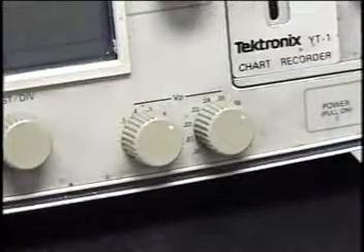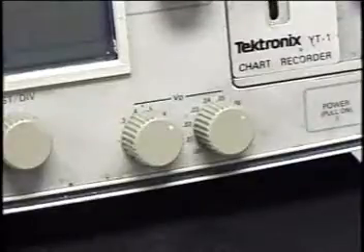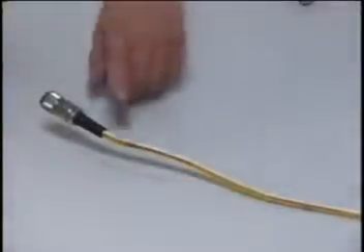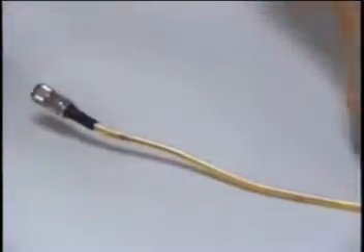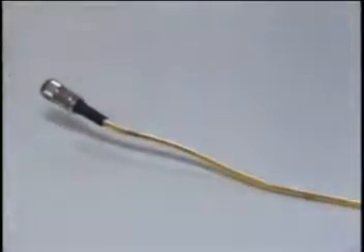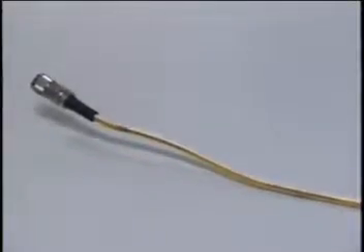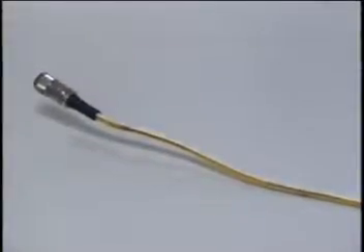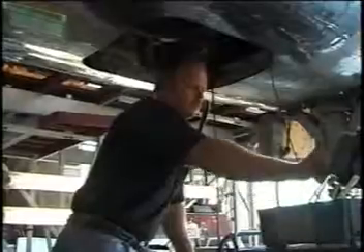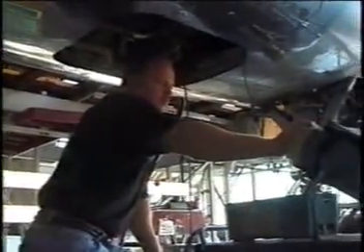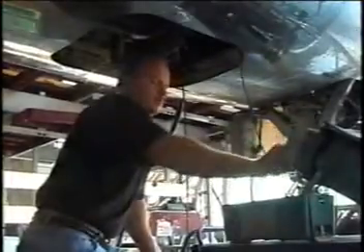With the cables properly bled and connected, you must then select the correct VP, or velocity of propagation setting. VP is the speed at which a signal travels down a cable and varies with different types of cables. Make sure you know the VP of the specific cable you wish to test, and set the TDR accordingly. This is crucial for determining the correct distance from the tester to any faults in the cable.